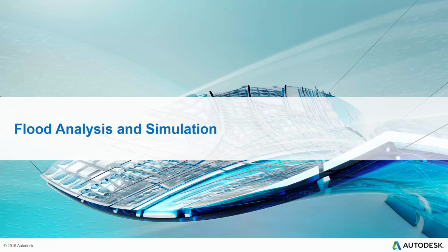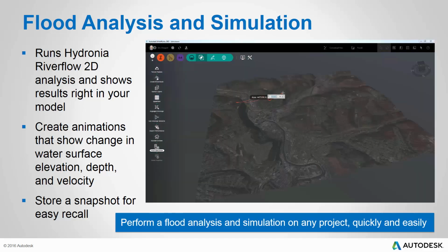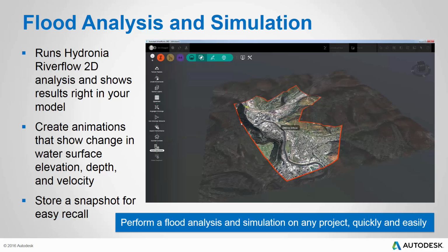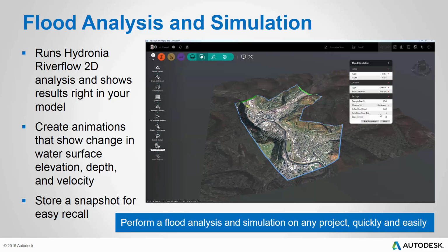Next, let's take a look at how flood analysis and simulation have become a part of this new release of InfraWorks 360. If you've got the latest release of InfraWorks 360 and Hydronia Riverflow 2D, you can run a flood analysis and simulation right in your InfraWorks 360 model. I'll start by defining the boundary that I'd like to study for my flood analysis. Then I'll define the inflow and outflow locations, and then provide the necessary values to run the flood analysis. I'll click Run Simulation,